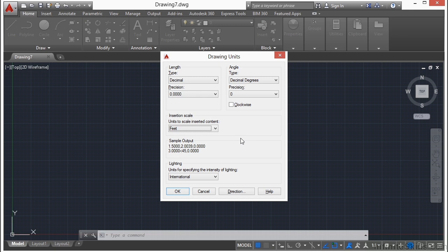Now, this is good for several reasons. 1, you are always creating an accurate drawing by drawing it to scale. And 2, your drawings will be properly drawn to scale when printing. And 3, others that need to use your file will know exactly what's going on with your line work. They can trust it. They know that, hey, this is drawn at 3 meters wide. It's 3 meters wide. So typically AutoCAD users will work with one set of drawing units, whatever they are.